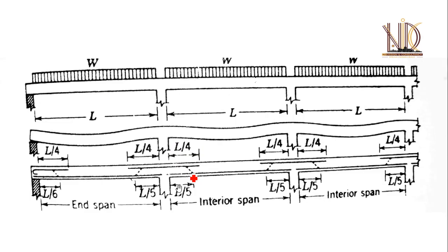So we can say what the tension zone is. The bottom layer of the middle section of a horizontal member and the top layer of the supporting zone is known as the tension zone. So we have to avoid this tension zone for providing lapping.